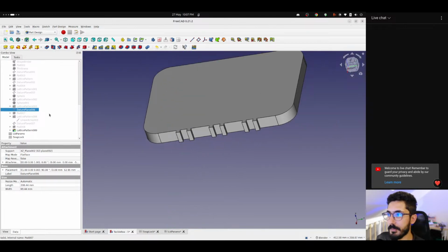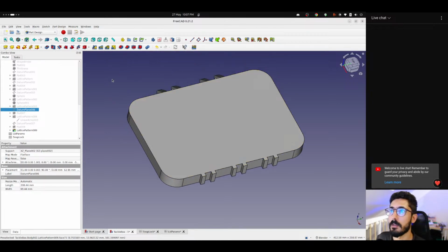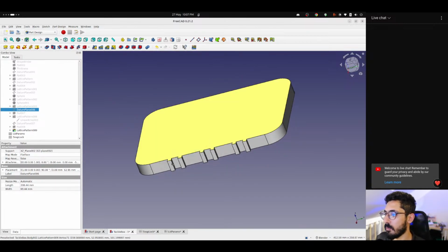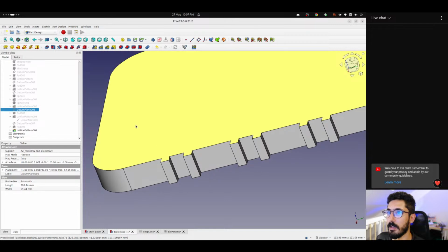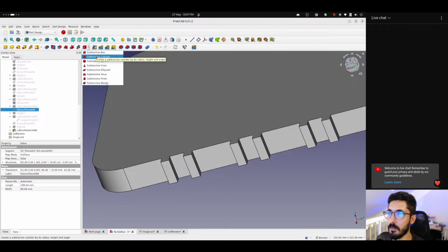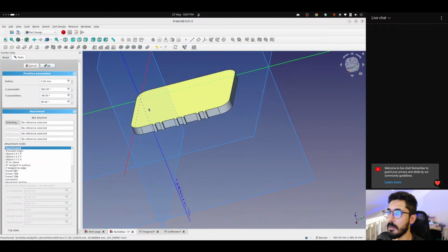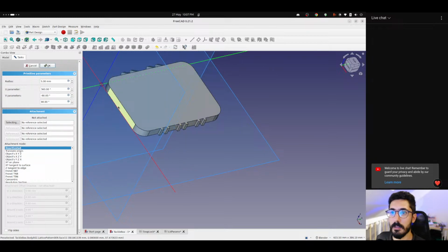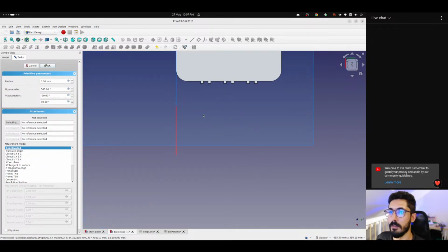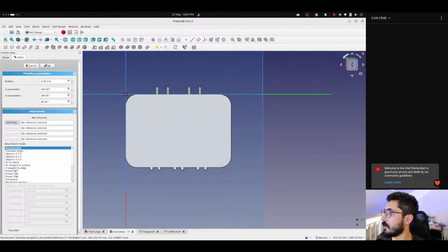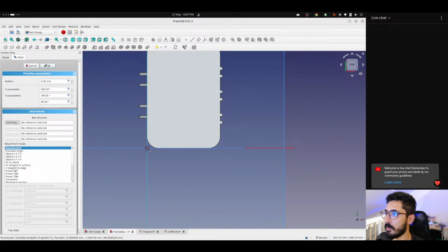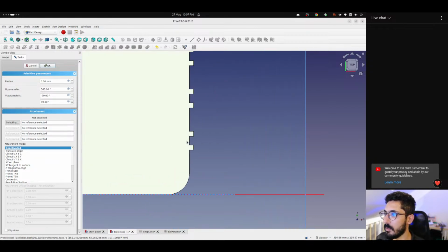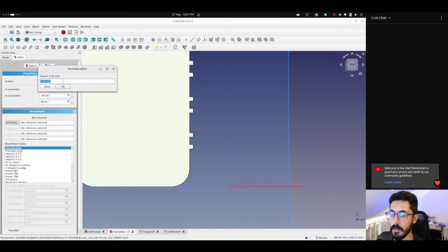Or yeah, nah. Let's just, so here we need to cut a sphere, not add a sphere. So we're gonna go with the subtractive sphere. And let's see, if we don't attach it to anything, what's gonna happen? I think it's fine. It's gonna attach to the origin anyways, and now we can move it here. Let's change the radius. So this is gonna be the snaplock dot ball diameter, but it's a radius, so divided by 2.